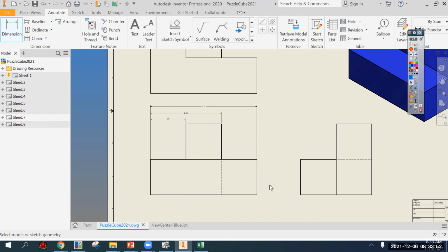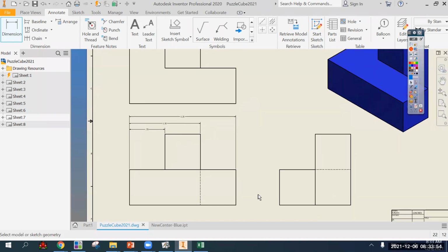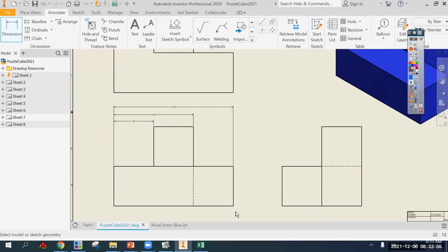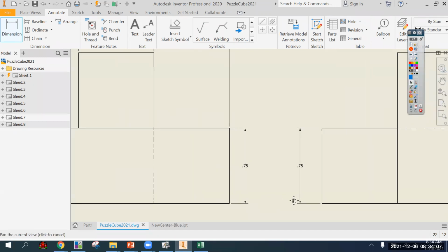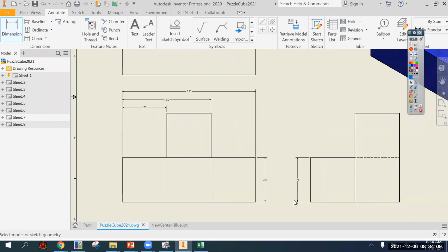Boom. Okay, now we do height, bottom to top. Going from the bottom up, the first thing that happens is this notch right here, this first block high, and that's fine. It could go here on the front view or here on the right side view. Not both places, because it's redundant.